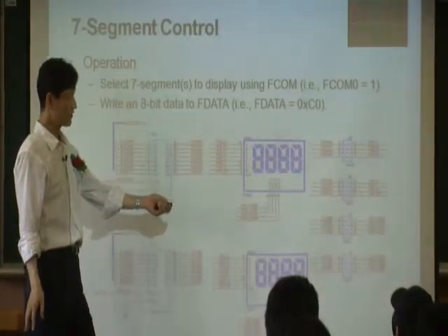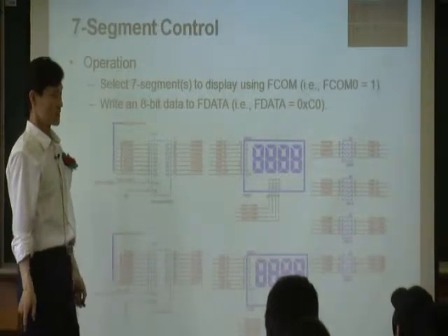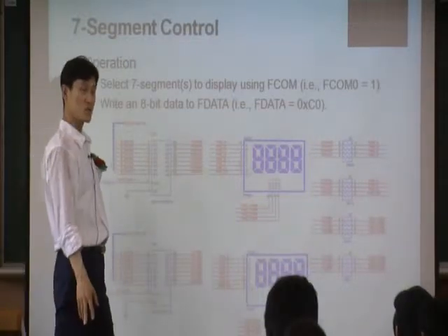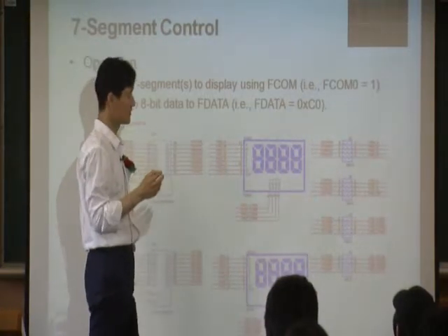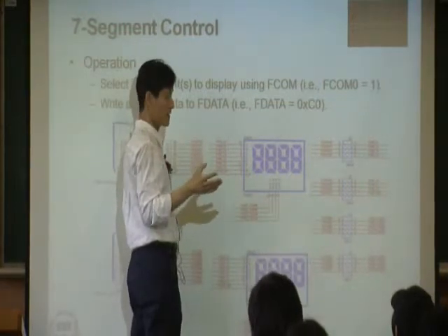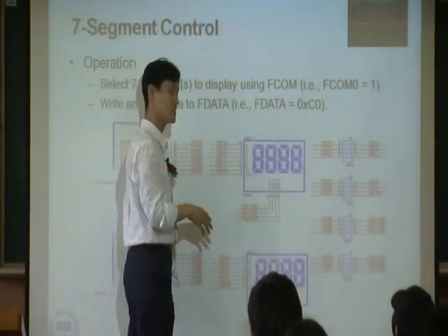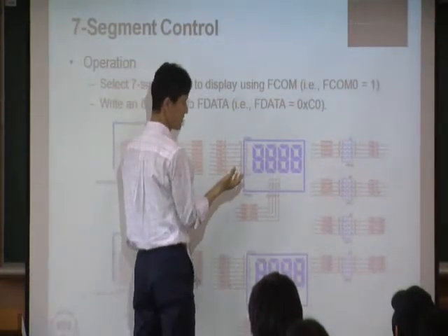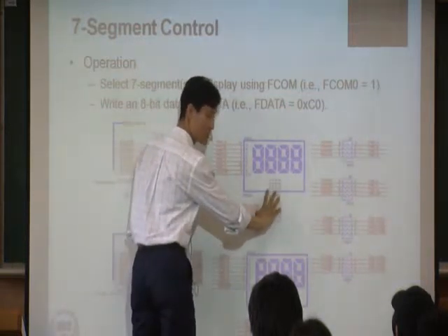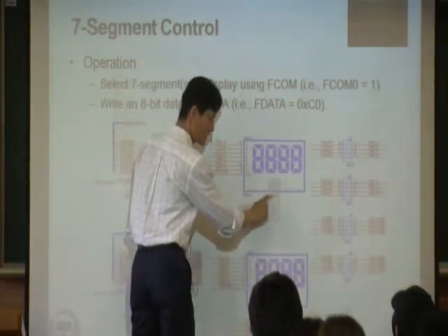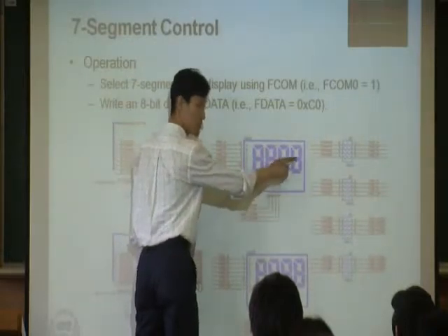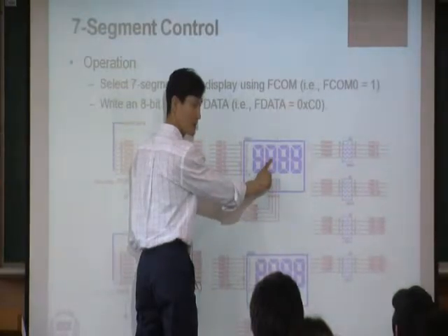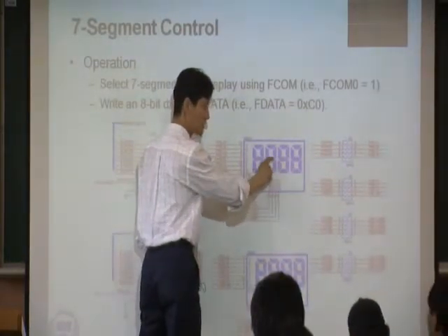Okay, that's a good point. We have 4 pins right here. So how can you do it? There is a trick here. It's a small trick: this device is cheating your eye. Here's how things work. We have 4 pins here, right? Each pin corresponds to each of these 7 segments. First pin is connected to this, second pin connected to that. So each pin is connected to each segment.